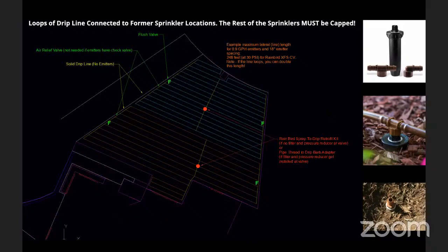And if you want to really learn about real details for this retrofit process, including how you might assess your landscape design and your current sprinkler design for a given area, and then decide on the retrofit, whether to go with a higher efficiency spray retrofit, whether to go with these retrofit kits, or whether to install a larger single header and install the pressure regulator and filter back at the valve, we have a whole workshop just focused on that. It's called Retrofitting Spray Irrigation Systems for Waterwise and California Native Gardens, available on our YouTube channel.